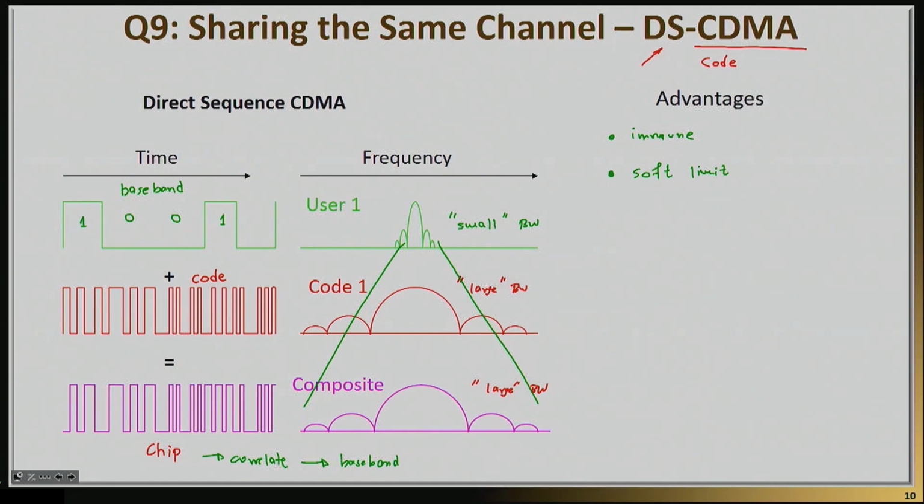basically increase the noise. So essentially what happens is, after a while, the noise is now high enough, you can't add any more users unless you're willing to, for example, increase the power, so the signal to noise ratio becomes again favorable. So that's why we call it a soft limit. You can always add users, but you have to pay a penalty. And that is actually much better than a hard limit, because I can always design my system to have trade-offs. I don't like basically hard limits.